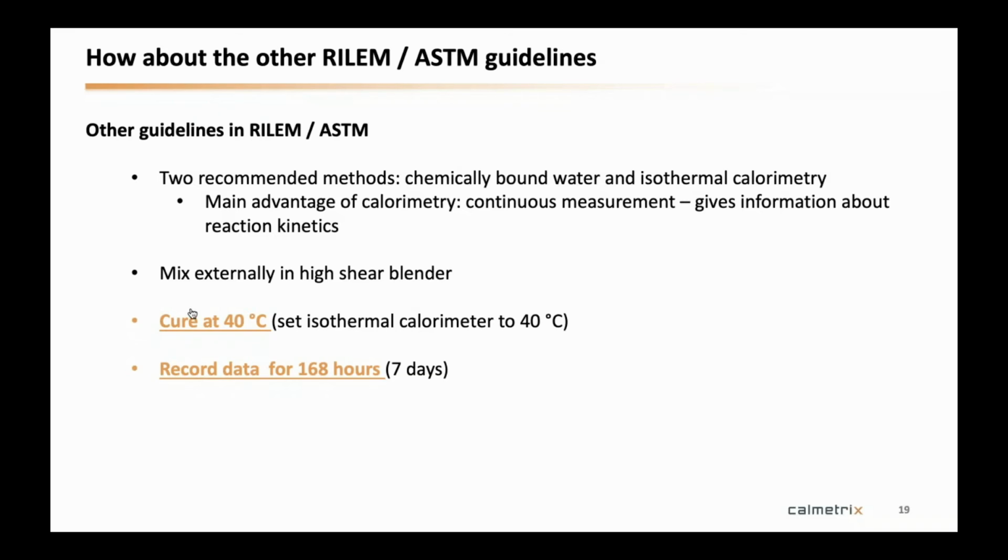I think related to that same point or same question, Neil Burke was asking, why not preheat materials? These materials were preheated. Even when you preheat the materials and you work at a calorimetry temperature that's close to ambient temperature, say you have an ambient temperature of 20 degrees C and your calorimeter is set at 23, there will be very little difference, because when you have the materials outside for a couple of minutes to do your mix, it's okay.